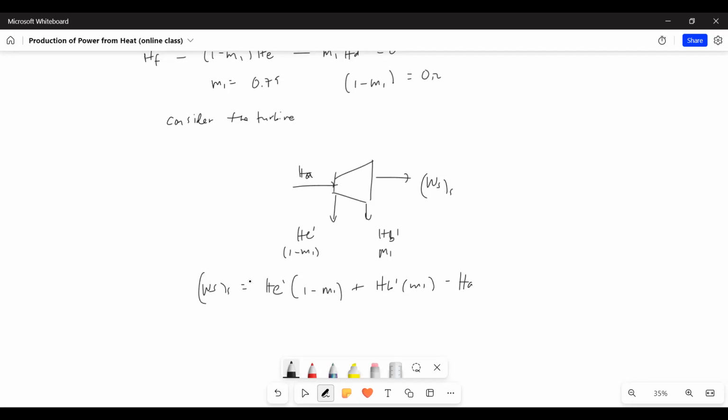So that's the energy balance around the turbine. So we know all of these values, lahat na except to. So we don't know this, and that's what we're solving for. Just substitute the values, and you will get negative 451.59 BTU per pound mass.